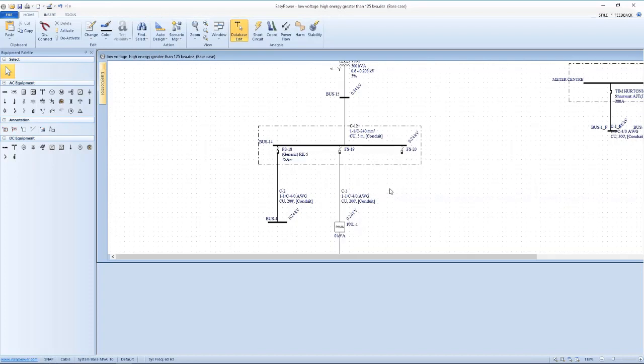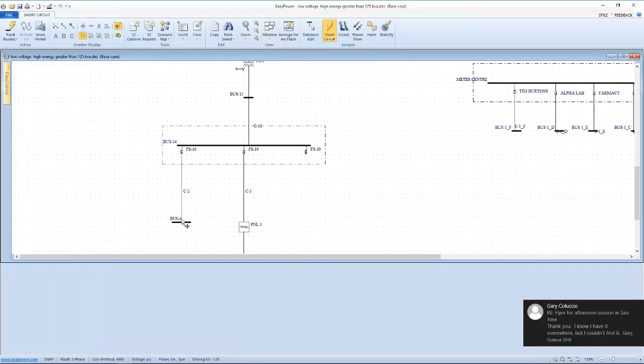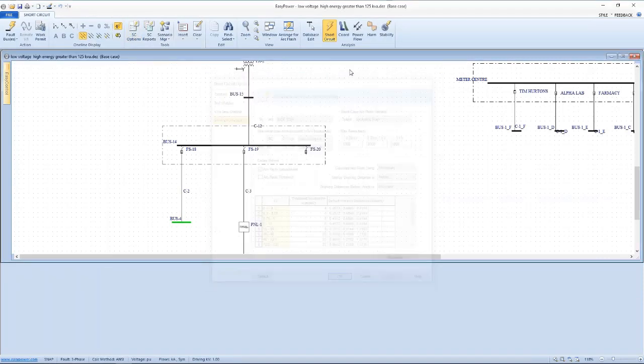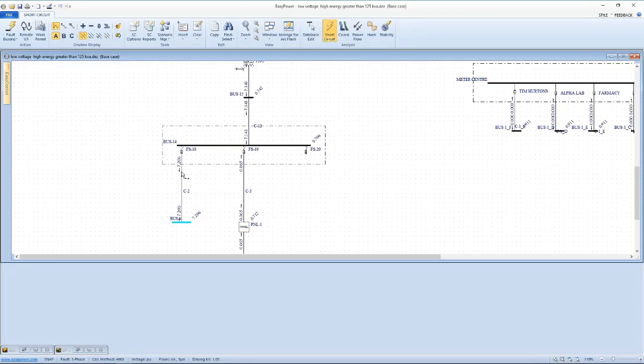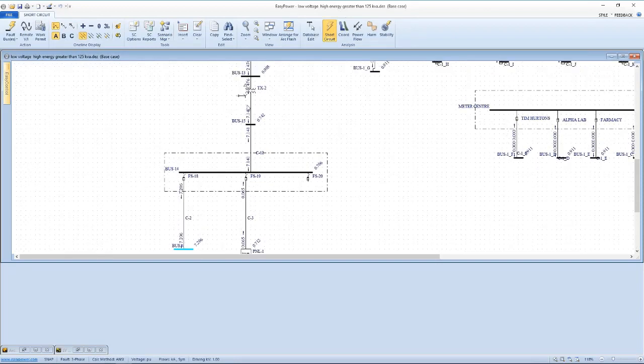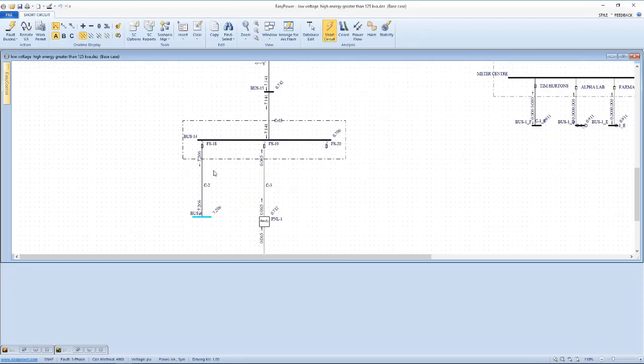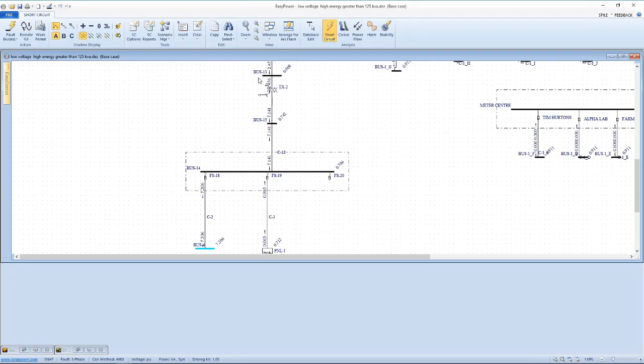So what we're looking at, if I look at fault current, let's say for this particular device, I don't want options, I want to go to short circuit current, fault this bus. So this 7,000 amps represents the voltage applied from this transformer and all the impedance between it and the utility source. So I guess what I'm suggesting is you have to do the math to know the total impedance path from here to the source of the energy.